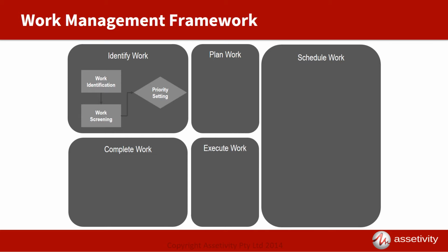The best way to manage all of these risks is to thoroughly plan the work ahead of time and to accurately document the task sequence, hazards, materials, labor, tools, and any other relevant information in a well-structured work pack that the maintainers can access at the job site. We call the preparation of this work pack job planning.